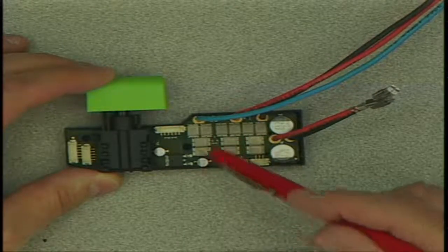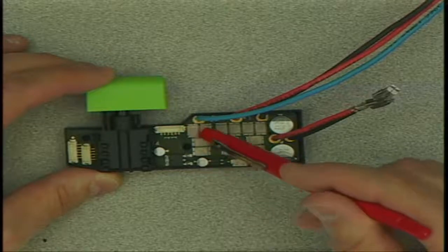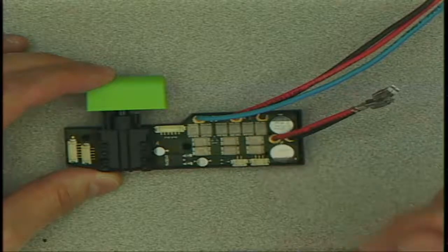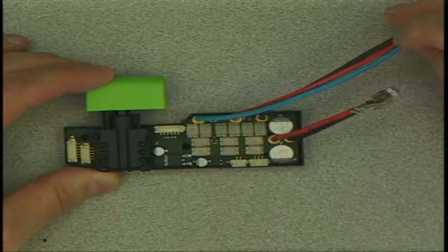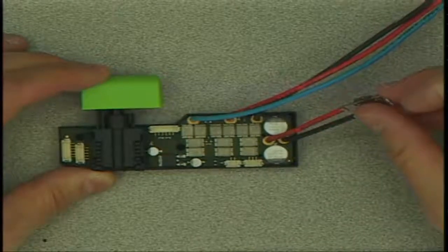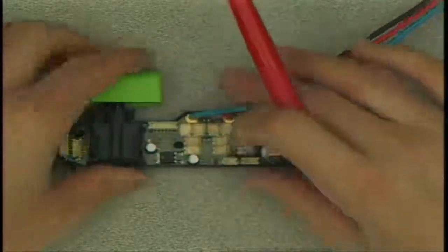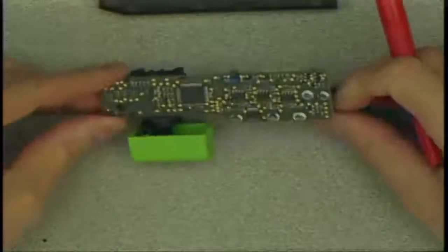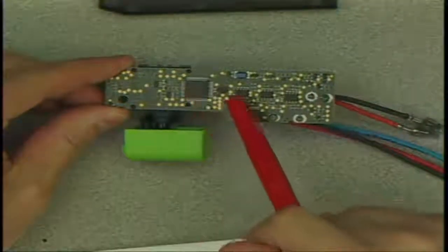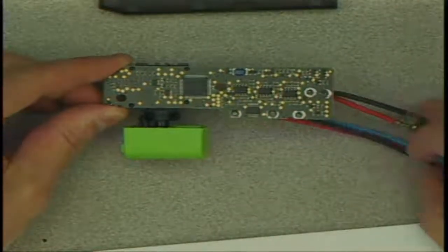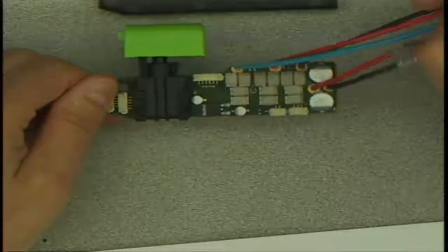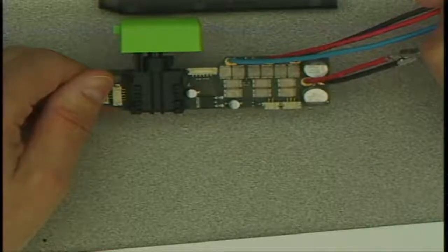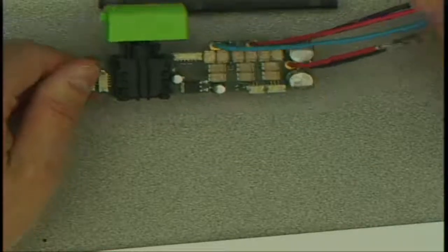There are 6 switches, each of them comprised of a pair of FETs in parallel. So there's 2, 4, 6, 8, 10, 12. And here are the 3 leads that go off to the motor, and this is the power lead here. It's a pretty interesting little package the way they do this. You can see here's the controller, and here are the gate drivers. So everything is on this little board that goes into the handle of a drill and powers 500-600 watts. So it's pretty impressive.